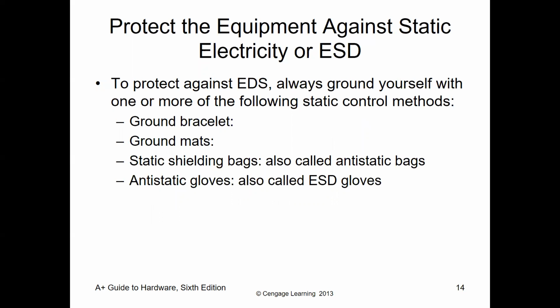Protecting the equipment against static electricity, or ESD, continued. To protect against ESD, always ground yourself with one or more of the following static control methods. Ground bracelet: always use an ESD strap, anti-static wrist strap, or ESD bracelet. Attach the bracelet to the computer case to ground it.